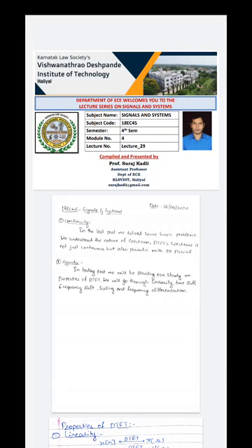In the last video lecture, we did solve some problems on discrete time Fourier transform and understood the nature of its spectrum. Discrete time Fourier transform's spectrum is continuous and periodic with respect to 2 pi period. And from DTFT's spectrum, we can draw magnitude spectrum and phase spectrum separately. Magnitude as well as phase spectrum will also be continuous and periodic with respect to 2 pi period. But magnitude spectrum of DTFT will always be an even function and phase spectrum will always be an odd function.